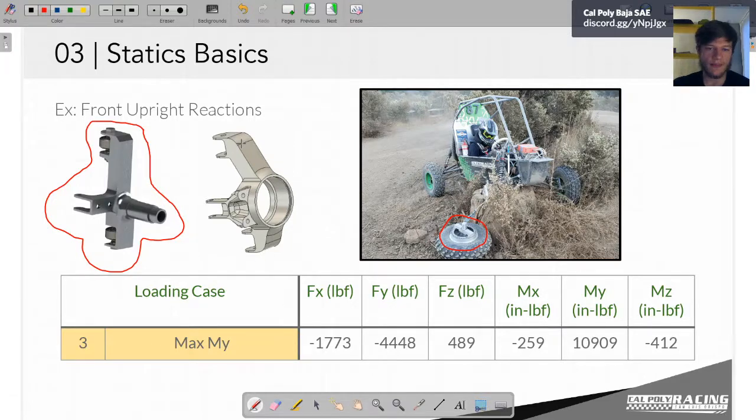There were some geometry things that were changed according to this data. But if we use this year's design with last year's data, then all of our directions are going to be slightly off. So we're going to analyze last year's uprights, which are the ones that the wheel force transducers were on, the ones that we used for testing.